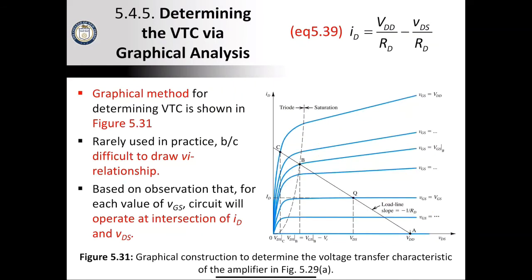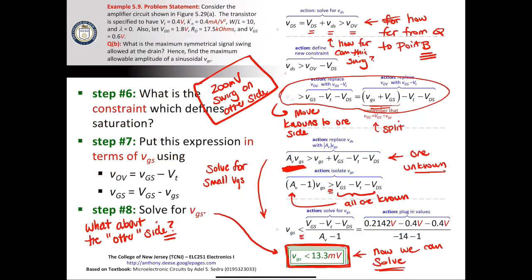Now, that doesn't take into account the linearity of the function because, right, we said that worst case scenario, we have to stay in between A and B. But if we make our range too big, things will start to become increasingly nonlinear, and that'll hurt the quality of our amplifier. But they didn't take that into account in this problem.